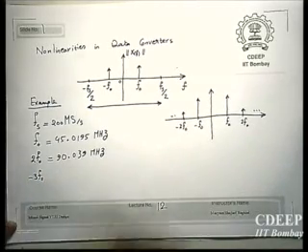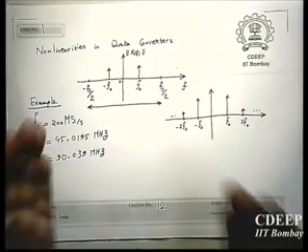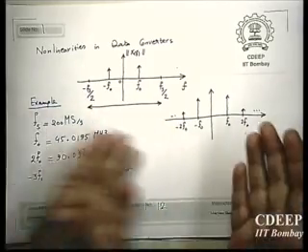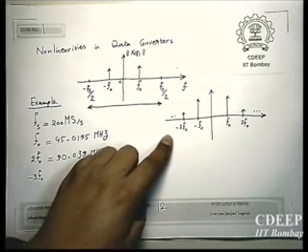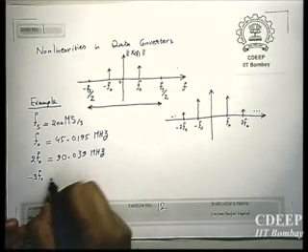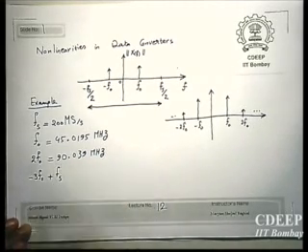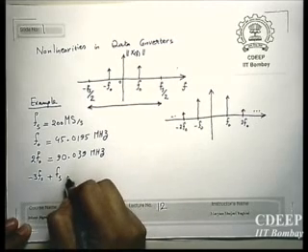Okay? Minus 3f0. If you add this by fs, because when you do sampling, you will have the main spectrum, then shifted by fs, shifted by minus fs, again shifted by 2fs. Now you look at the spectrum which is shifted by fs and the frequency component of minus 3f0. Therefore, you will have minus 3f0 plus fs. Now this will be in your band, right? So now if you calculate, it will be